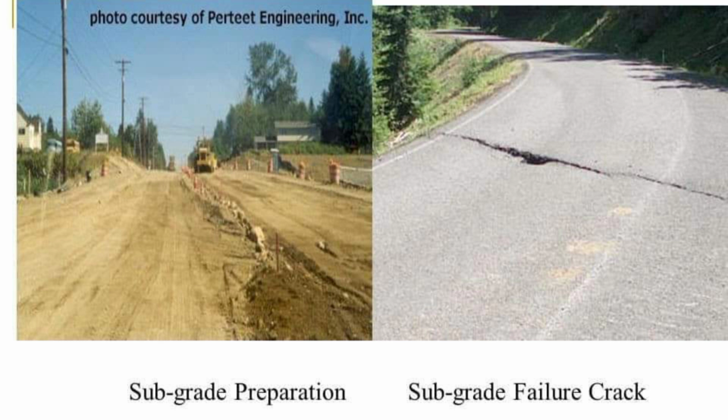We also call it clearing and grubbing, which means you have to clear the ground of bushes, etc. If the subgrade is not properly prepared or not compacted, in practical terms we call it NGC, natural ground compaction, so if NGC is not properly done, then you will have transverse cracks, and also you have to face